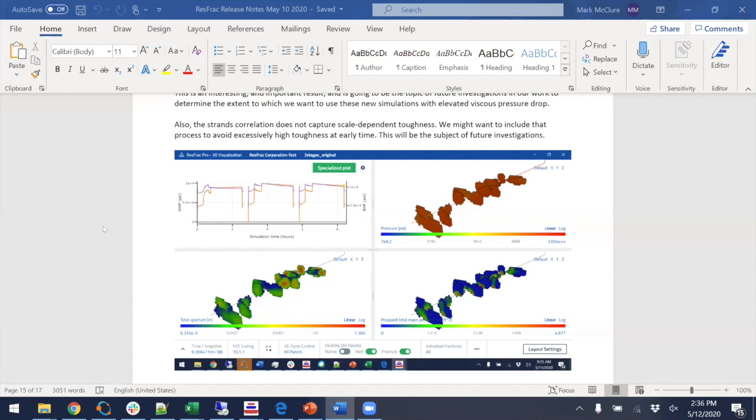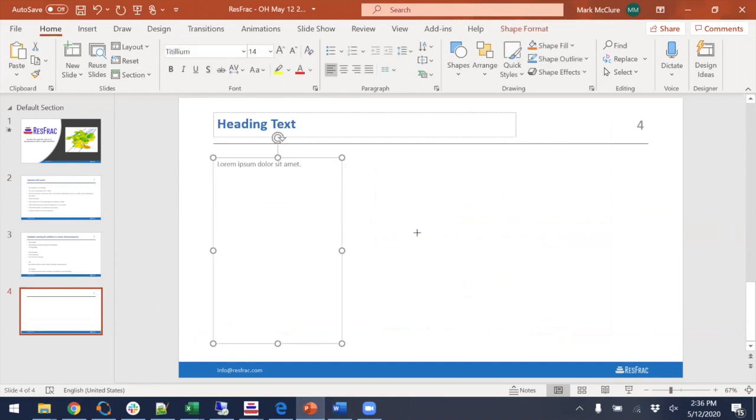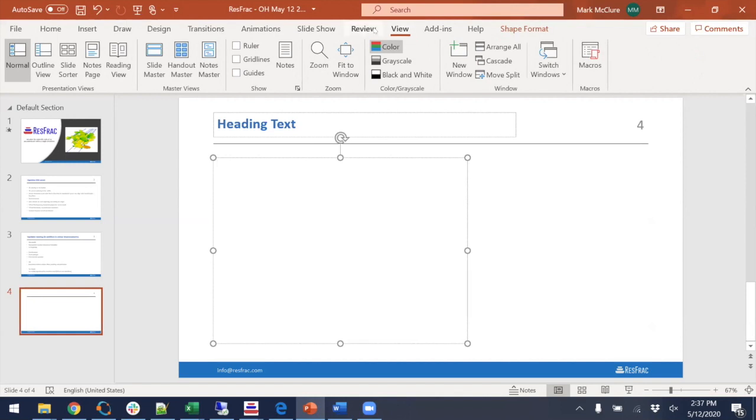That's where previously we had a PDP table, right, where in the ResFrac software, the thought was we're using a planar fracture to actually represent multiple fractures. And because there's that non-uniqueness between fracture area and permeability, to mimic the additional area from multiple fracture bands, we could input a PDP table where permeability was increased during injection and then reverted back to original during production.